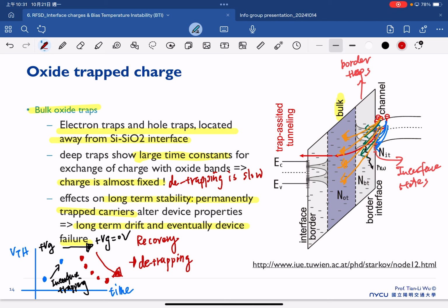I can fully understand that detrapping sometimes is a word whose meaning is not precise. Also, sometimes it's an effect you cannot visualize. You cannot visualize an electron being captured; it's difficult to visualize this phenomenon. It's not like a completely open, short, or complete breakdown where you see certain damage. The trapping effect is happening inside the dielectric, so you cannot visualize the effect. But what we usually do is come up with electrical characterization to try to visualize this effect. So this is one of the examples.